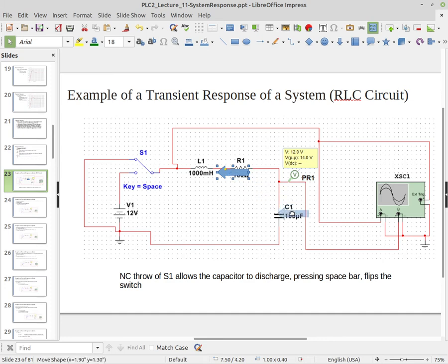And so what happens is, when you have an inductor and a capacitor in the circuit, they basically give you this oscillation. You end up charging up the capacitor, but once the capacitor starts getting to full charge, it says, I don't want any more current, so it tries to stop the current. But the inductor's like, no, I don't want you to stop.